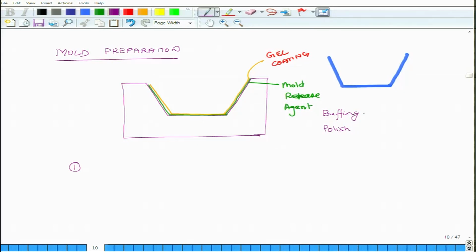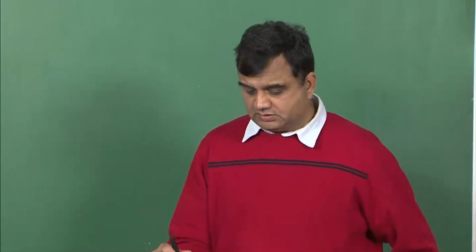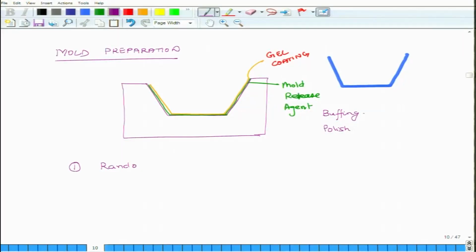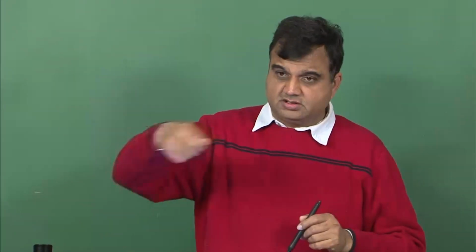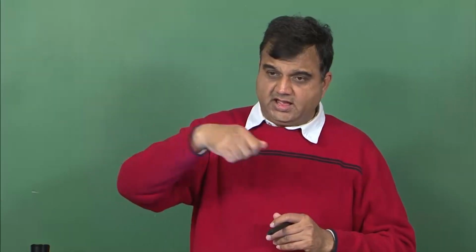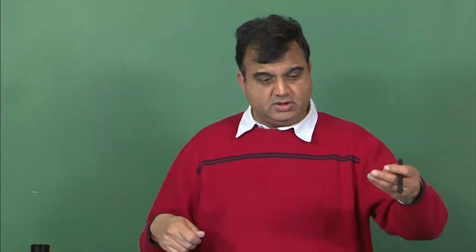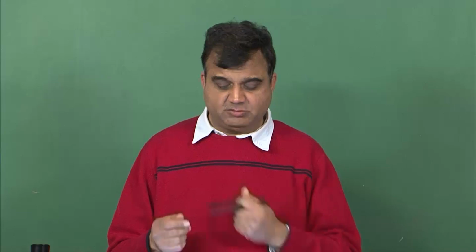Okay. So, if the fibers are randomly oriented, then what you do is you have small length of fibers, and through some nozzle you spray them, and because you are spraying them they fall in all sorts of orientations, and you keep on spraying it on top of the mold, and while you are spraying it on top of the mold through another nozzle you also spray matrix in fluid state simultaneously.